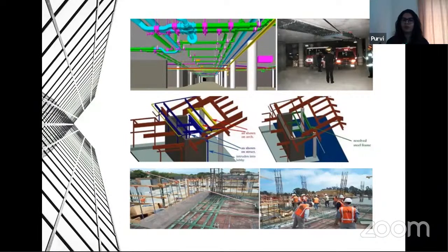So it is always advisable that you first coordinate your model in Revit amongst all the three verticals. You will have a lot of errors. You will resolve those errors in each file, and once you have done the coordination and set the shared coordinates for the whole project, that's when you will be bringing it into Navisworks for further clash detection.